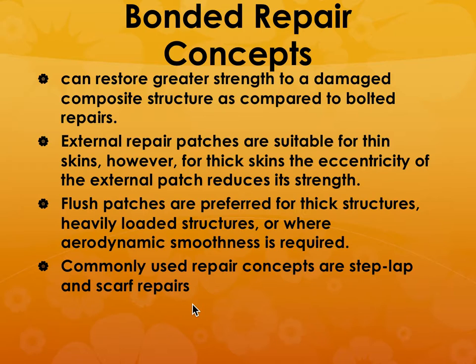So bolting is not the most ideal composite repair method. The most common and useful repair concept for a composite is bonding. And why? Because it can restore greater strength to a damaged composite structure as compared to the bolting type of a repair.